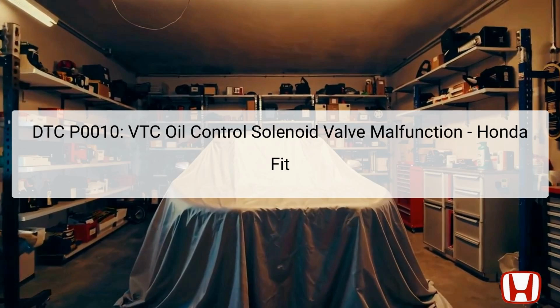DTC P0010 indicates a malfunction in the variable timing control (VTC) oil control solenoid valve for the Honda Fit model years 2015 to 2020. This solenoid valve is essential for controlling the flow of engine oil to the VTC system, which ultimately helps optimize engine performance and efficiency.